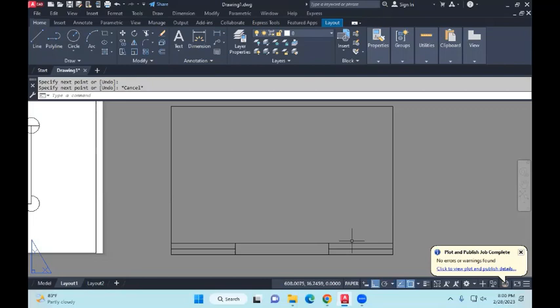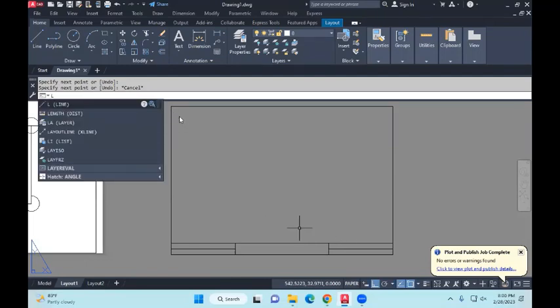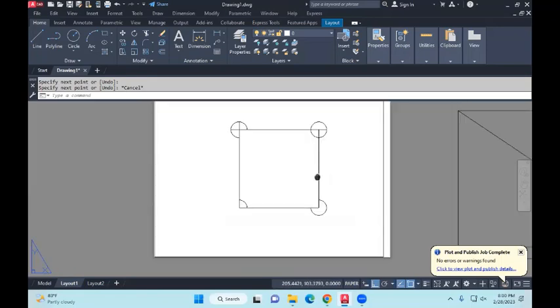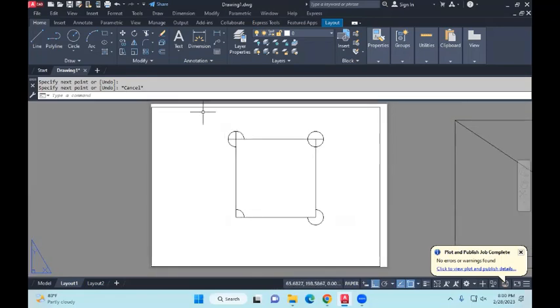Now you need to paste the title block on the page, isn't it? The title block goes on the page. The page is in white. The gray area is pretty much nothing. So the way we do this is I will draw a diagonal line from the top left corner to the bottom right corner. Set. Okay, done. Now I'll come here on the page. I have my viewport. I'll do the same thing. I'll draw another diagonal line from the top left corner to the bottom right corner. Right? I have two diagonals, one on the title block, one on the page.